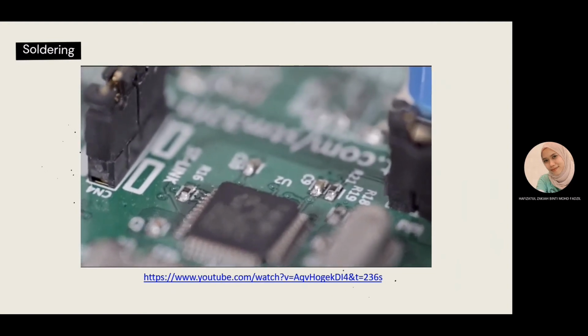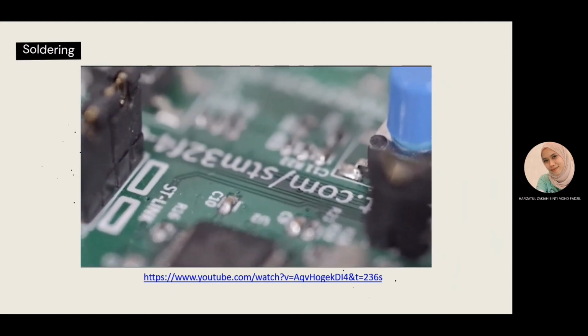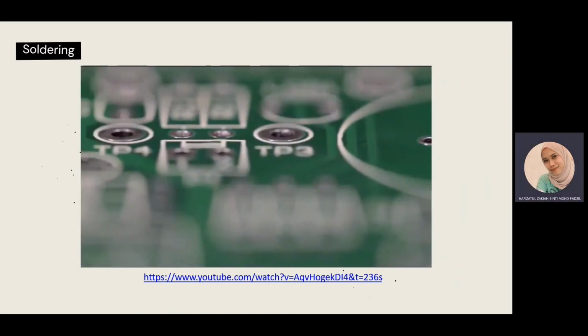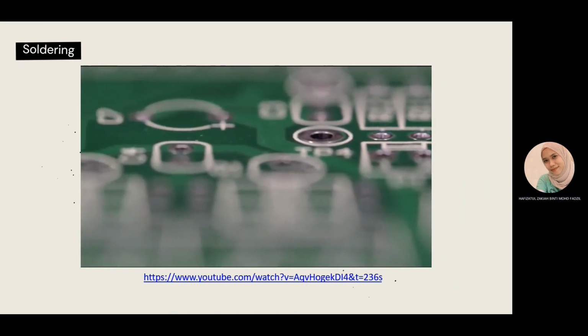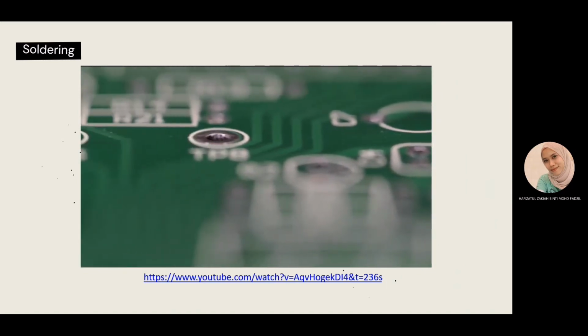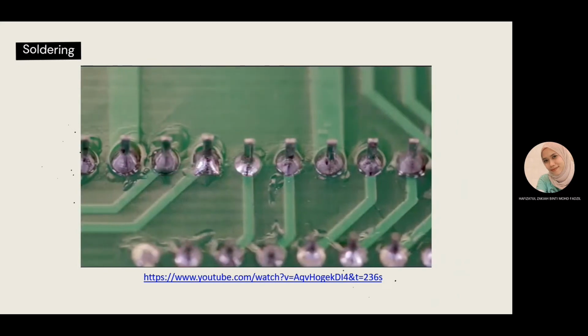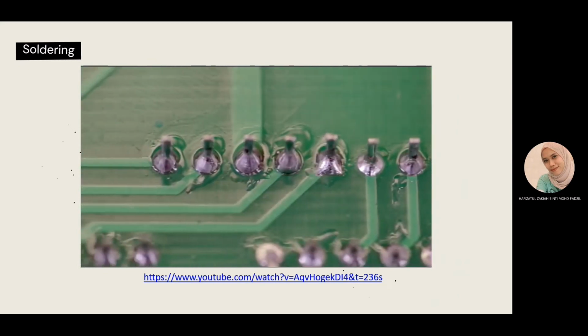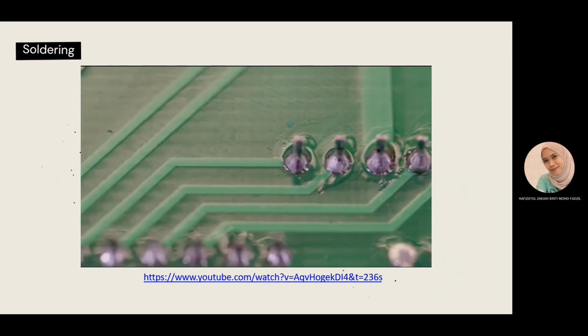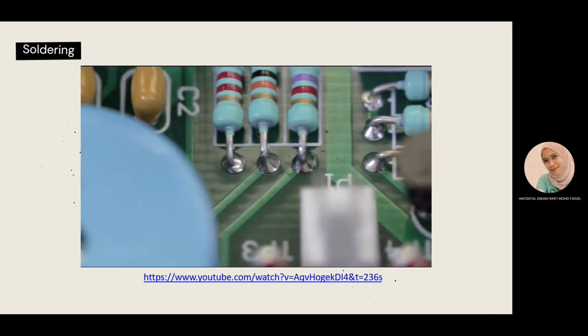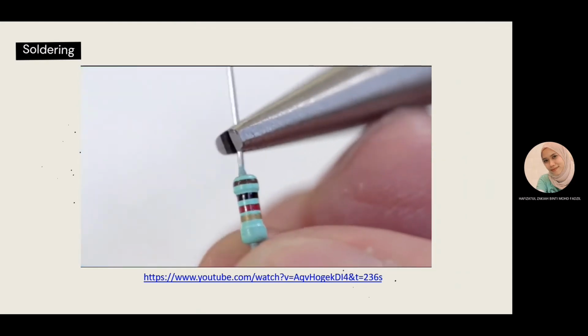Surface mount connections are made by heating components with pre-applied solder in an oven so that it melts and joins to the surface of the board. For this tutorial, we'll look at plated through-hole soldering, which is done on boards with printed circuits on both sides. Through-hole soldering is when components are pushed through a hole in the board and soldered from the other side. The solder flows through the hole to make the best possible contact.